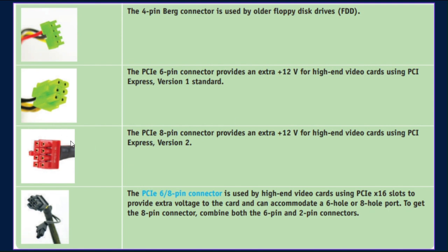This in the red is the PCIe 8-pin connector, which provides an extra plus 12 volt for the high-end video card using the PCI Express version 2. This is the version 1 and this is the version 2. The version 1 has 6 pins and the version 2 has 8 pins.